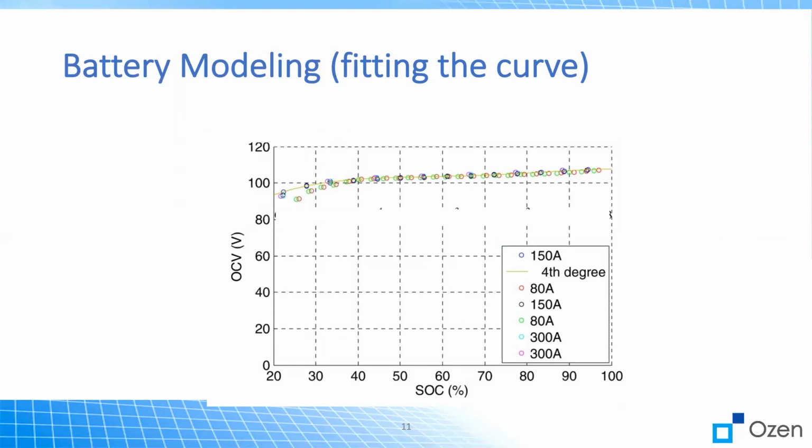measured at different points. So, long story short, if you plot OCV based on SOC at different currents, this is how it looks like. As you can see, they all converge here, meaning no matter what the current is, OCV has the same behavior. There are some points where you don't see a convergence here. The reason is that the battery was not rested for a long time. If the battery was rested for much longer than 10 seconds, these points would eventually converge too.